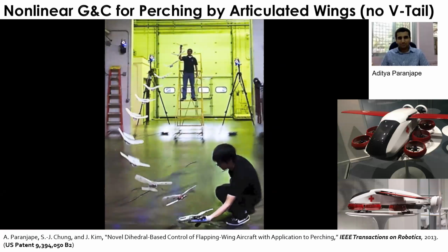And then you can also extend that to bounded input, bounded output stability, because the stability from contraction theory is exponential and global. And it's actually easy to combine multiple systems. For example, I don't know how to use passivity to prove the stability of a hierarchically combined system, but it's kind of trivial if you use contraction theory, as you can see in this example.